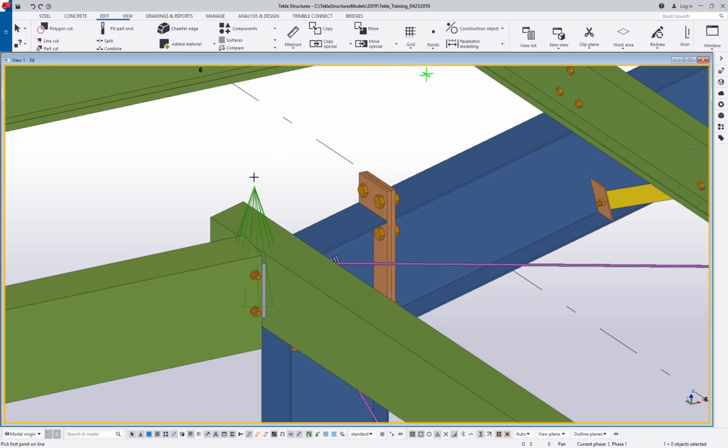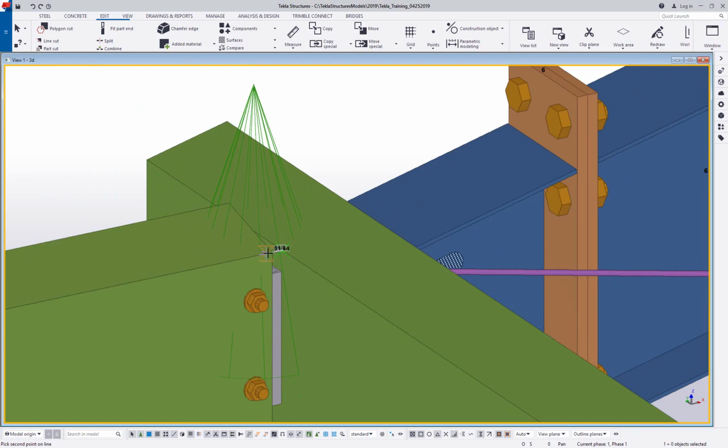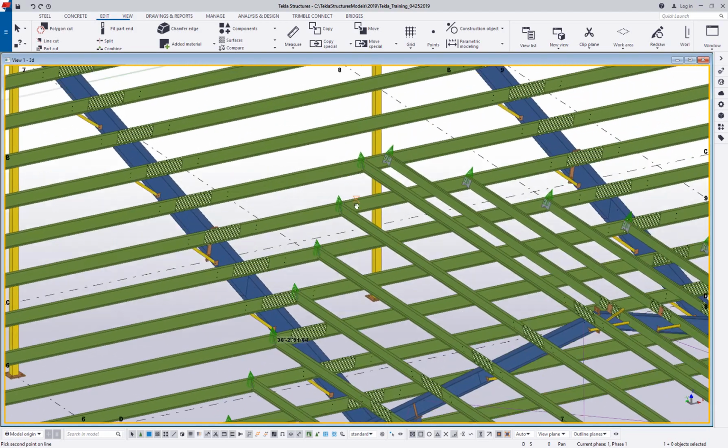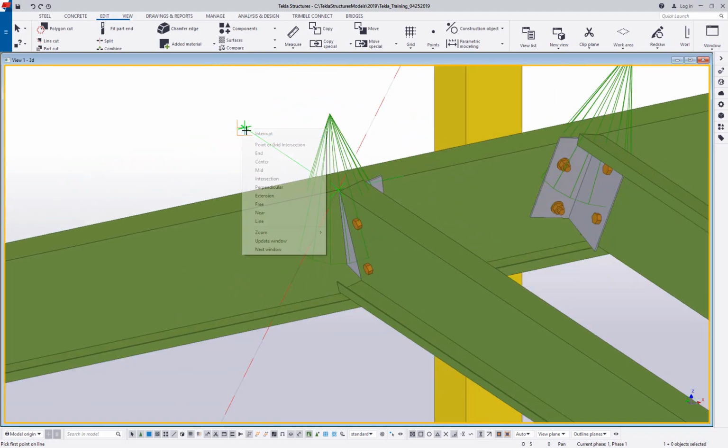In this case, I'm just going to go from this point here, basically if I were to project that eave member over to meet this one, and then we will throw this construction line down where this purlin would have met the roof purlin. So a slight adjustment there because I already had a connection. If I did not have a connection yet, it might be a little bit easier to find that point.